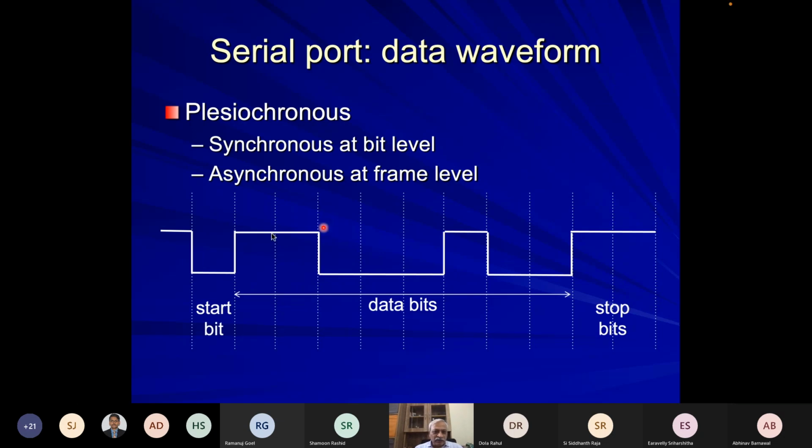So now, since they have clocks which are nearly the same, there may be a phase difference, but the phase change will not accumulate too much within one data word. But the next one could come at an arbitrary time. So this gap between 2 words could be arbitrary, and the receiver has to ensure that it detects this phase. So timing will start counting from this point onwards.